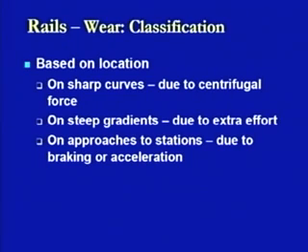In both cases, whether we are talking about braking efforts or acceleration effort, the force will be acting on the top surface of the rail section, and when this force is acting at the top surface, it may stimulate or cause wearing of the top surface of the rail section. So, this is another reason, or another location, due to which the wear of the surfaces may take place.